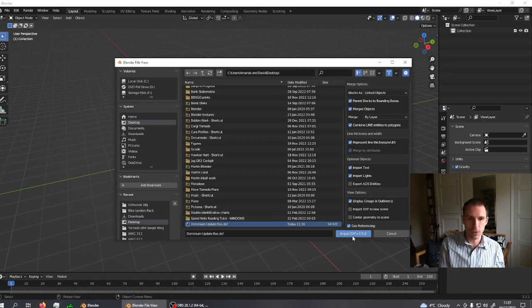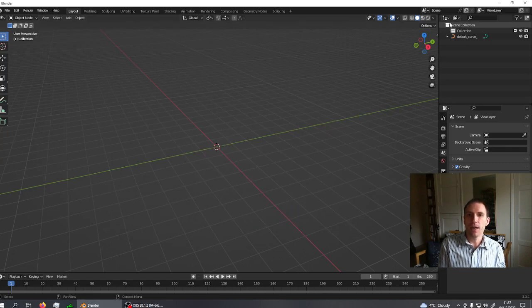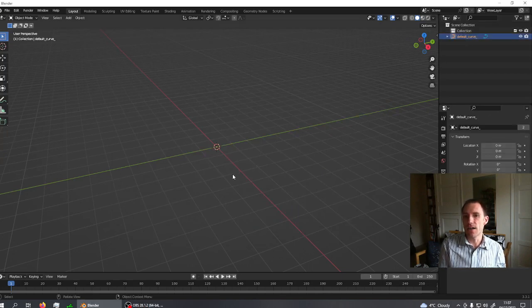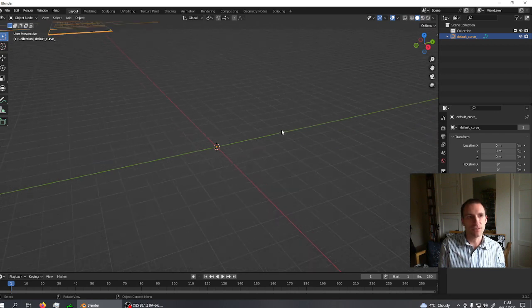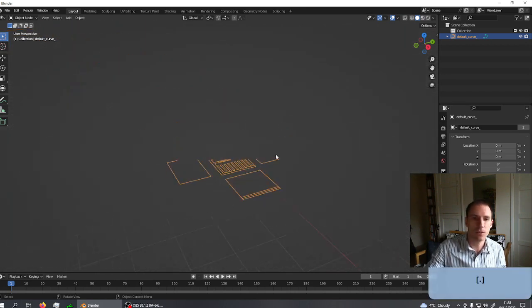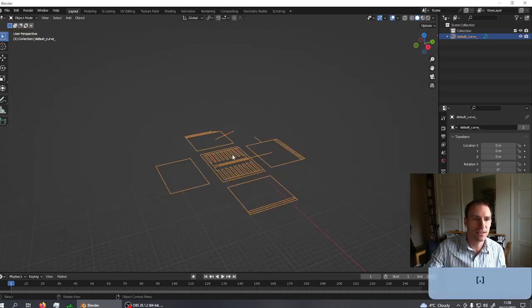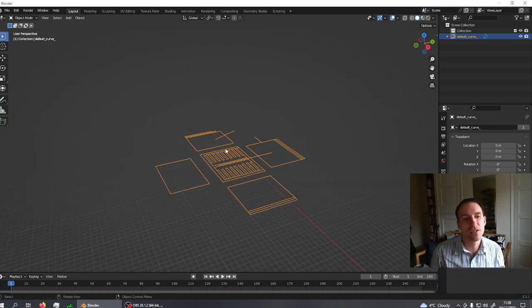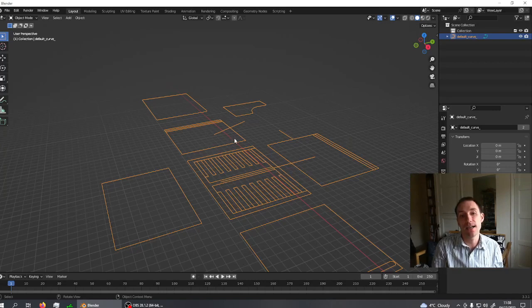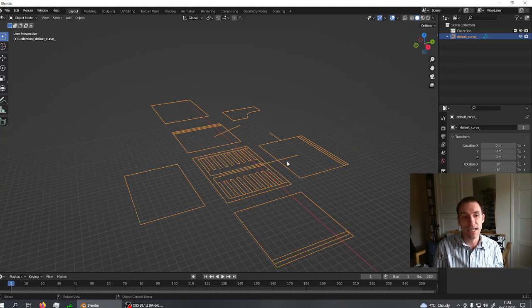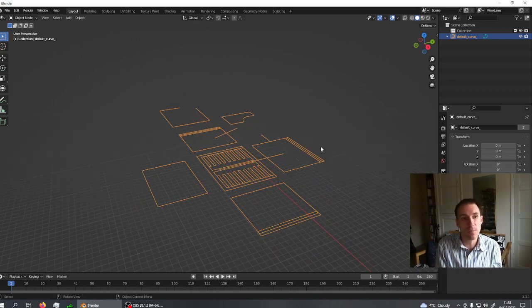There are some options, and boom, execute. And what you get is a curve. It imports as a curve, and if we press stop to go to the object, as you can see it's miles away, because I'm running in 1mm scale, so 1mm in DeltaCAD, and then here in Blender, if you're 3D printing, you take 1 Blender meter to be a millimeter. Now you can change the units, but I don't bother.